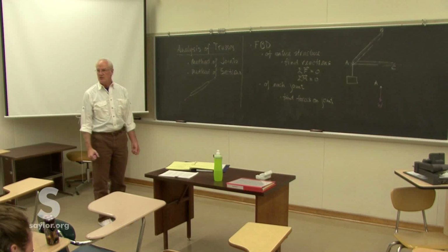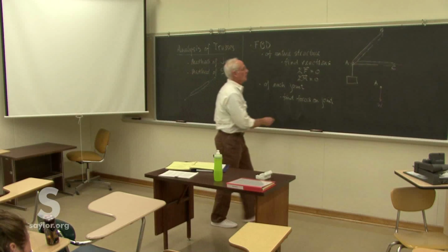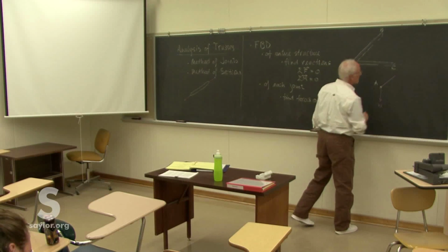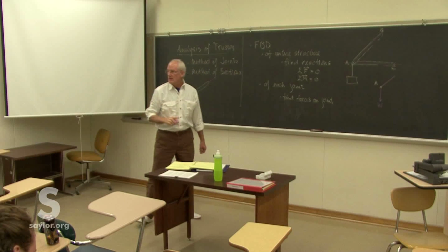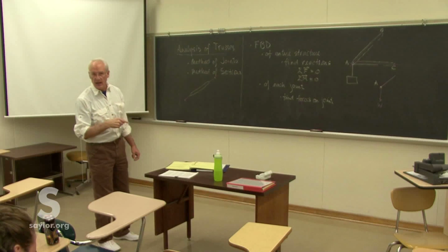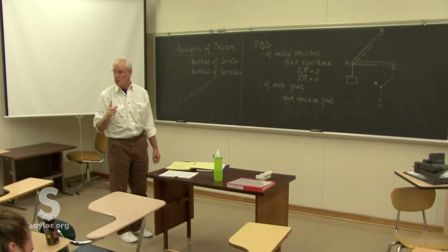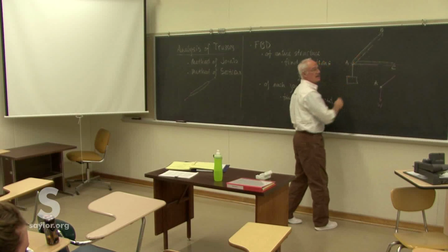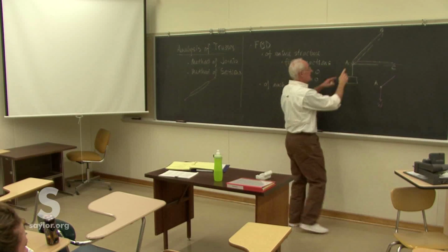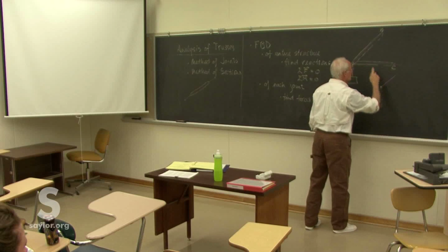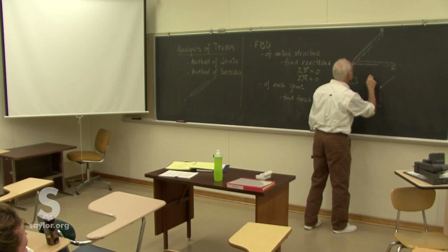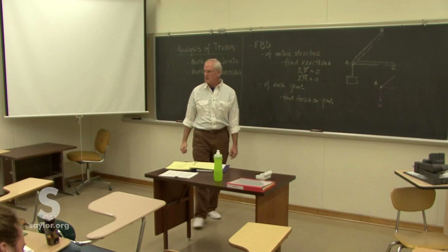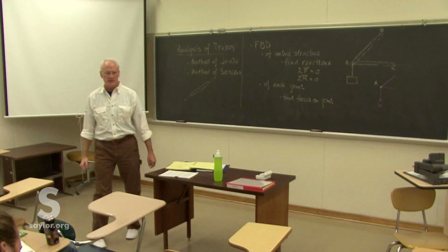That's good for us because we know then the forces involved there. We know there's one force that's going to go from A to B. We might not know whether it's pushing on the joint A or pulling on the joint A. It could do either. But we do know its angle. It's got to have the same angle as the member itself, at least the line connecting the two joints. If the member happens to curve, it doesn't matter to us. And so we have another one that's going to be in that direction because that's where the next joint lies.